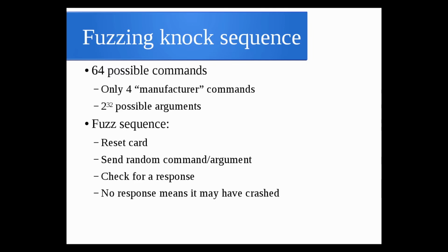Great. So what we're going to do is fuzz the sequence. We're going to reset the card: power it down, power it up, send command 0 to actually reset it. Then we'll send a random command with a random argument and check for a response. If it doesn't respond, or if it responds with a not-illegal-command, then we have something interesting going on. Maybe it's code execution, maybe not. If it doesn't respond, it probably means the card crashed, which is great.